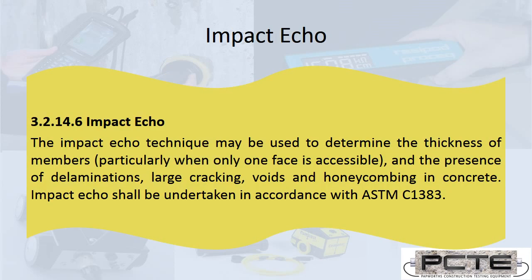Impact echo is another sonic test. The big advantage of this one is it's carried out from one side of the structure. So it can be used to assess the thickness and delamination, voiding, large cracks. It also gives an ASTM standard.